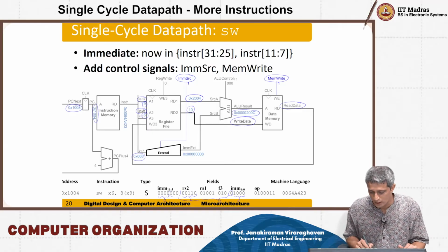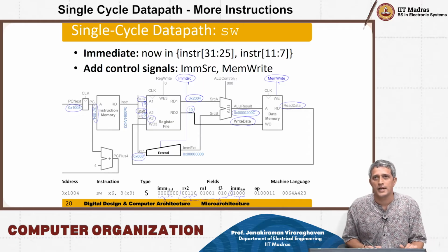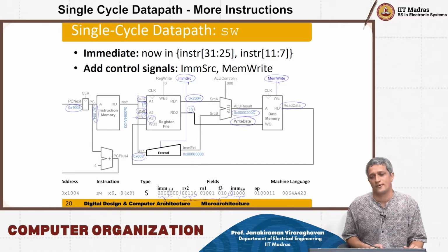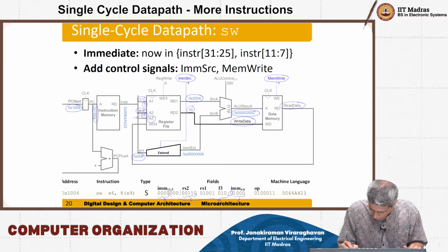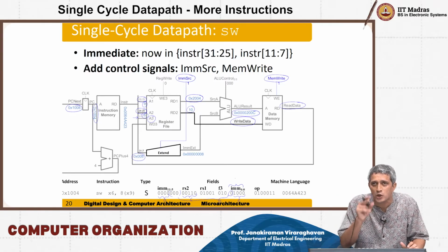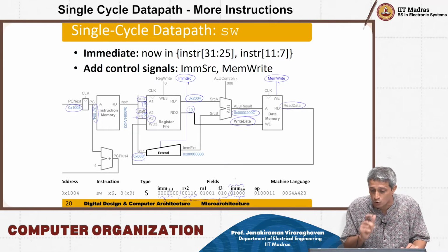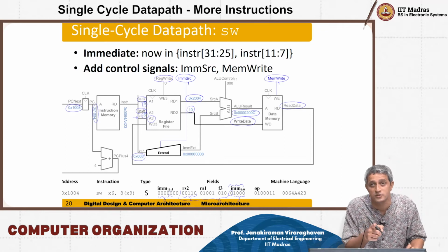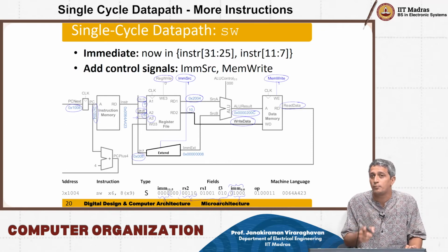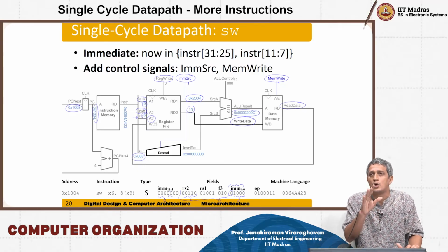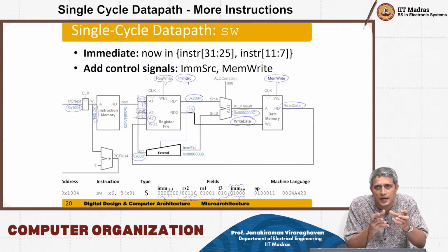For example, if you look at it, the A3, right, is getting bits 11 to 7, that is what is here, right, and that is getting some data, but does it mean that that is going to write into register X8? Answer is no. Why? Because this reg write signal has to be 0 for this particular instruction. So that's why it is important to understand that data can be written into a register not just by providing the address and the data.